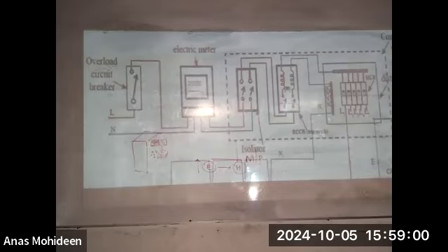That is a place where we are using most of the electric appliances, isn't it? Okay, so when you are using all these electric appliances, you have to make sure you don't draw more than the maximum current. For one gadget, only one electric appliance you have to connect. So let's say the current drawn goes more than 30 ampere. Now what happens? The MCB goes over. The second MCB has gone off, and it is connected to my kitchen, so I know the kitchen is the problem. I have to check only within the kitchen.